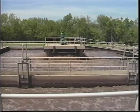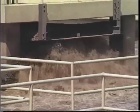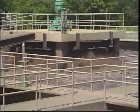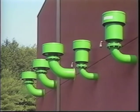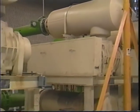The aeration system may be either mechanical or diffused air type of system. Mechanical aerators use mixers on the surface of the water to agitate the contents of the aeration tank and to introduce dissolved oxygen into the mixed liquor. Diffused air systems use blowers that push air through diffusers in the bottom of the aeration tanks.